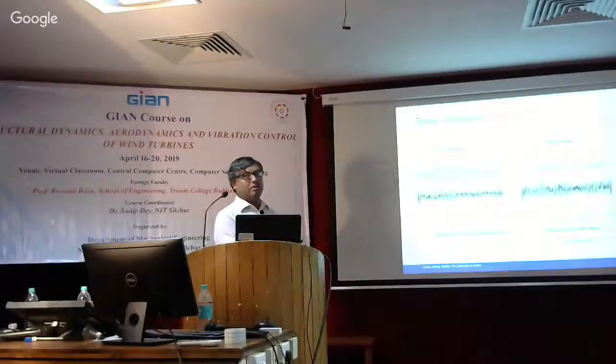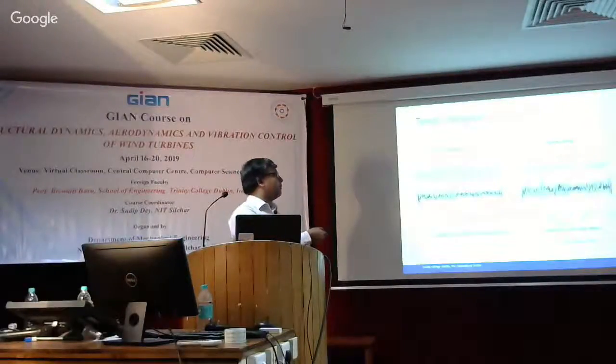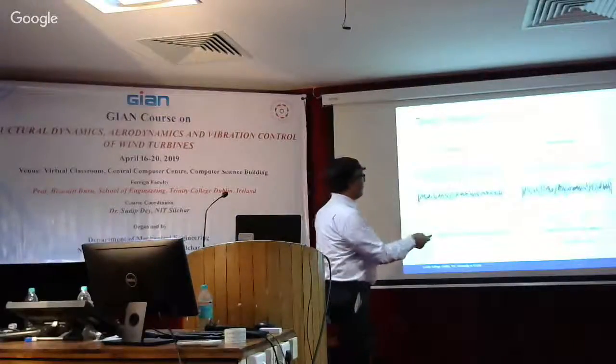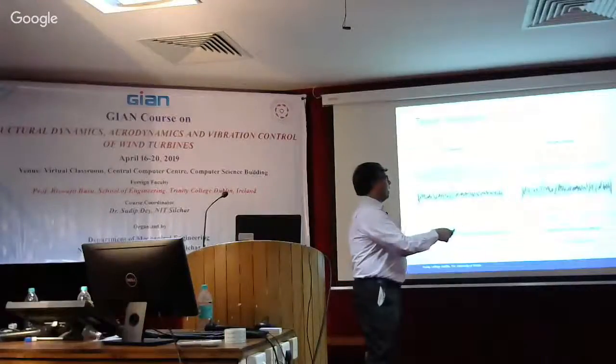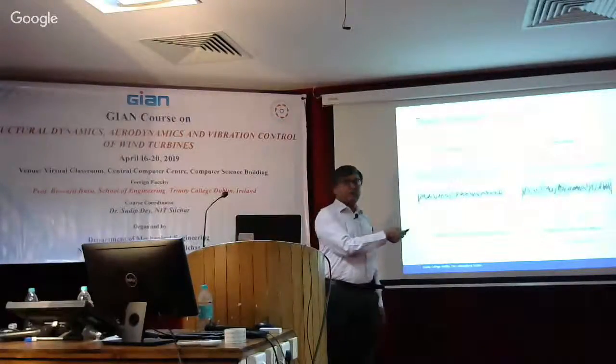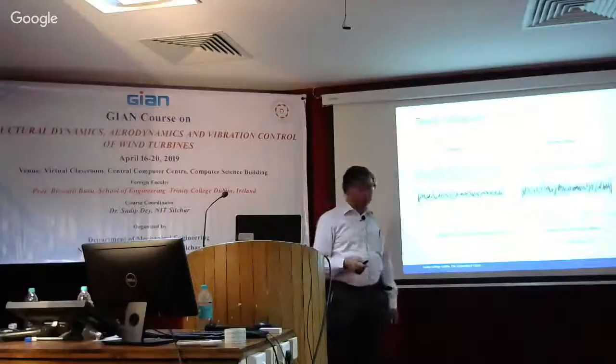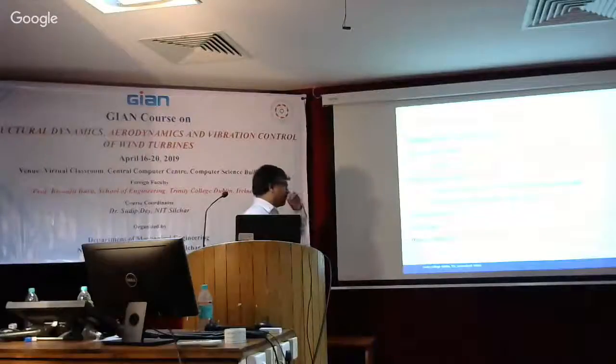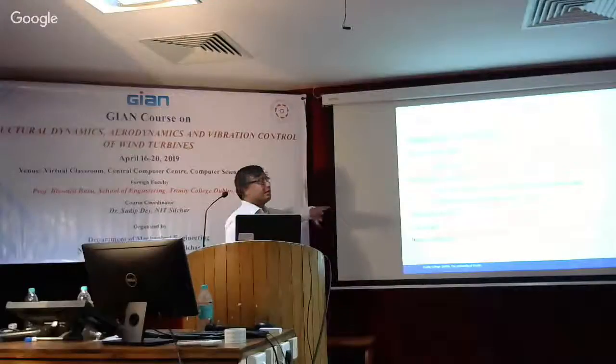What would be the reason? Because now we have activated the pitch. The pitch is being used to introduce the damping, meaning to introduce the additional force that we need to suppress the tower vibration. That delta. So that is why significantly our pitch angles are required. Pitch demand has gone up. Then you can design all sorts of advanced controllers with all these possibilities and combinations.